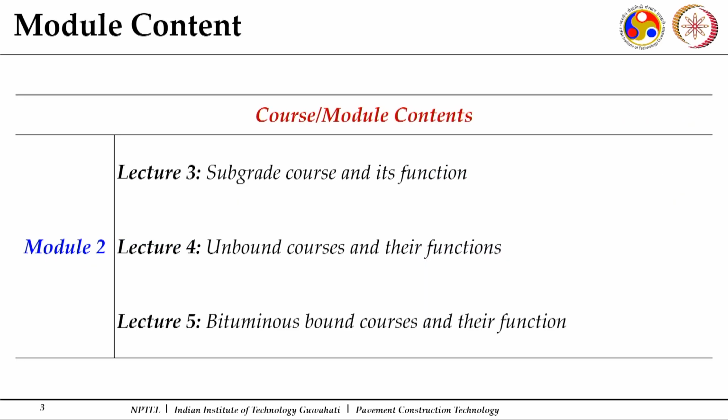Our today's lecture will be in continuation to lecture 5 on bituminous bound courses and their functions under module 2. In the previous lecture, we discussed bituminous mixes which can be used in base courses, binder courses, and wearing courses. We discussed the bituminous macadam used in bituminous base courses, the dense bituminous macadam which can be used as a base course and also as a binder course. Then we discussed the bituminous concrete mixes which can again be used in a binder course as well as a wearing course.